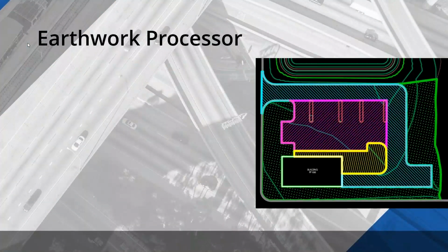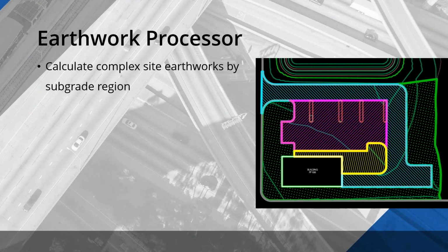So what is Earthwork Processor? For those of you who don't know, it is a robust tool to calculate complex site earthworks per region. For example, in the screenshot I have here, perhaps there are different hold down depths for different portions of my site, for heavy duty pavements versus light duty versus topsoil, that sort of thing. Earthwork calculations in this way can be quite complex. Earthwork Processor automates all of that for you.